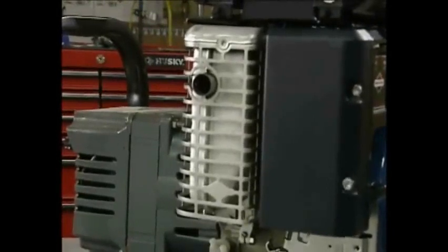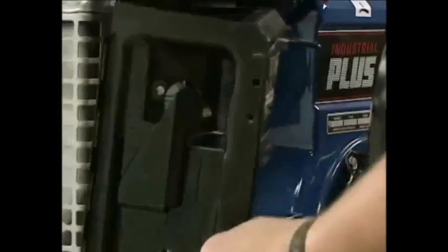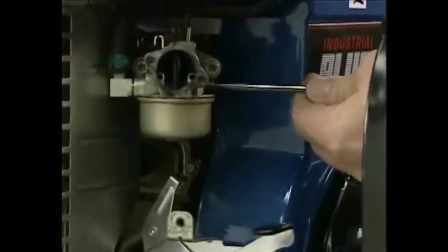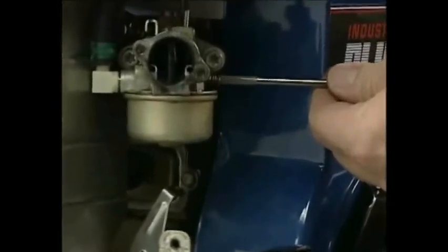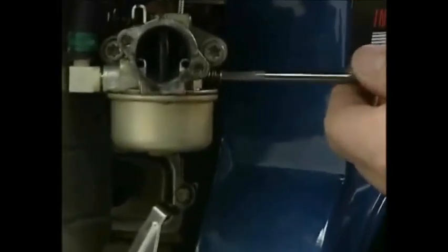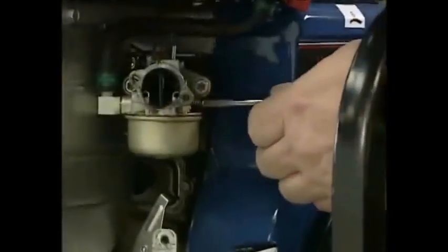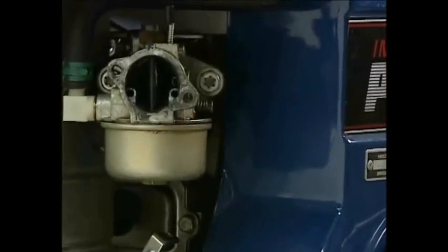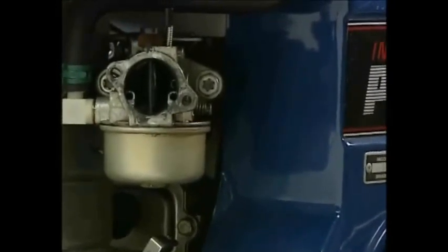If the carburetor has an idle mixture screw, you can use it as a diagnostic tool. While the engine is running, adjust the idle mixture screw until the engine runs smoothly. Shut off the engine, and while turning the idle mixture screw in until it bottoms out, count the number of turns. If the idle mixture screw was less than 1 turn out, there's a good chance the idle air circuit is clogged.